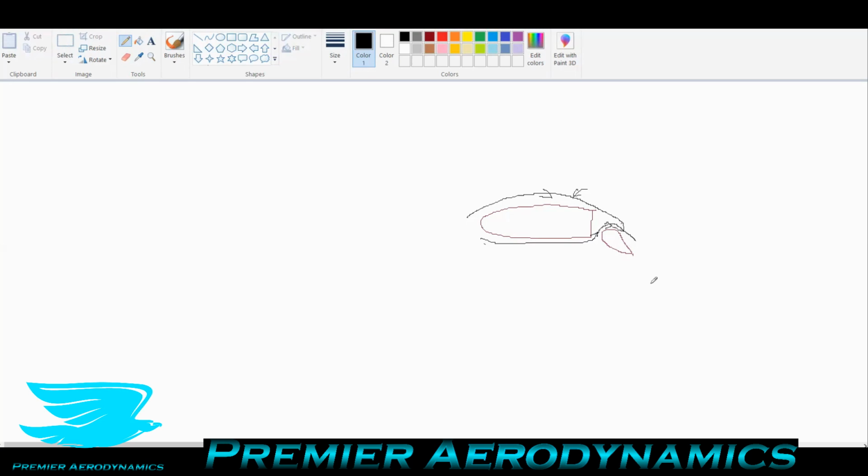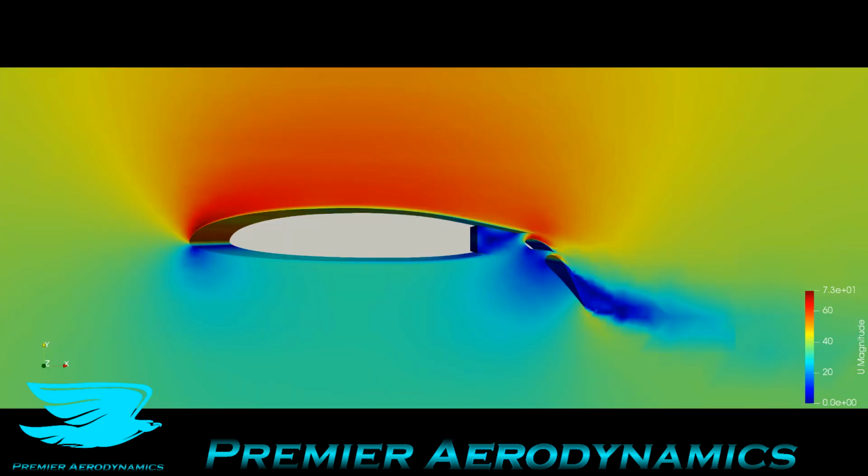And in this system, we have another airfoil underneath as well, and we have even more flow coming up and under to re-energize this flow and have what's called a high momentum boundary layer. So we're just mixing a lot of high momentum fluid. So I mentioned that some of the airfoil is stalling. Let's talk about which part is stalling here.